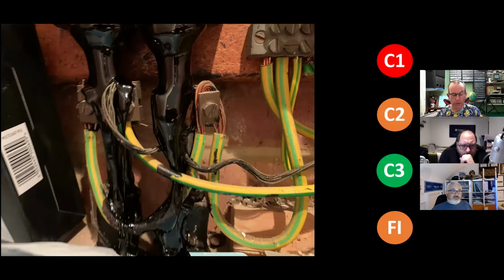Because the DNOs did experiment with other clamps while they were walking away from BS 951. Yeah, that coppery type is quite common around here. You see them all the time when it's not the 951 style. So the one on the left has two connections on it. Does the one on the right have one connection or two, and the other one's under pitch? I think it's just hidden under the pitch. It's just two bits of bent copper or material with screws in the end, and it just clamps down either side. They're not very good. They're usually loose and dropping off.